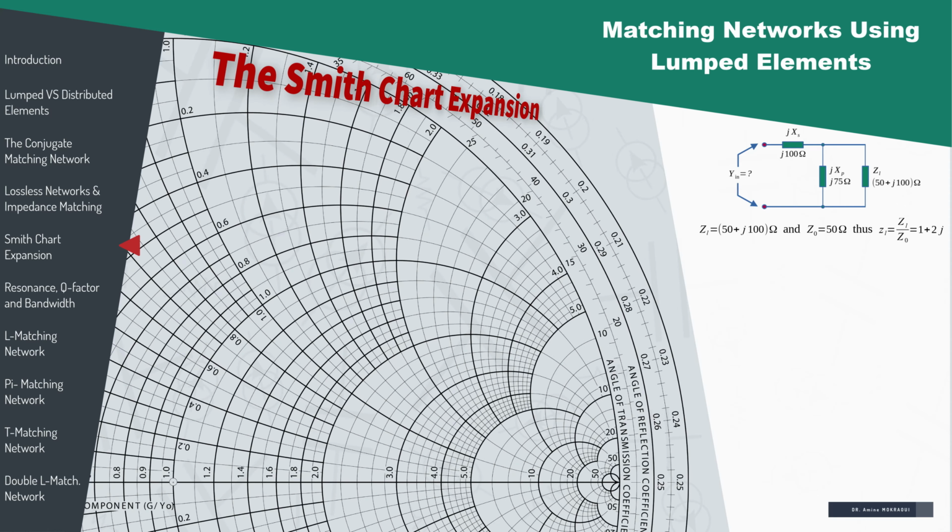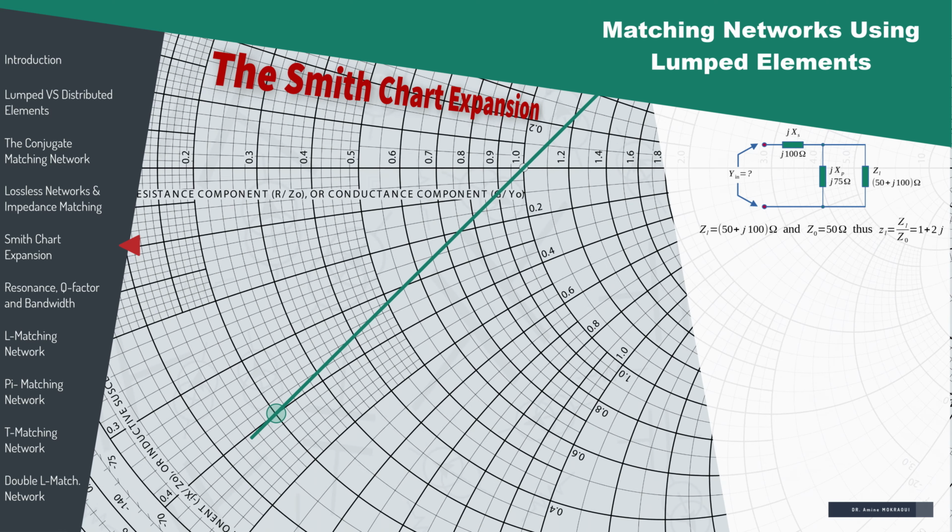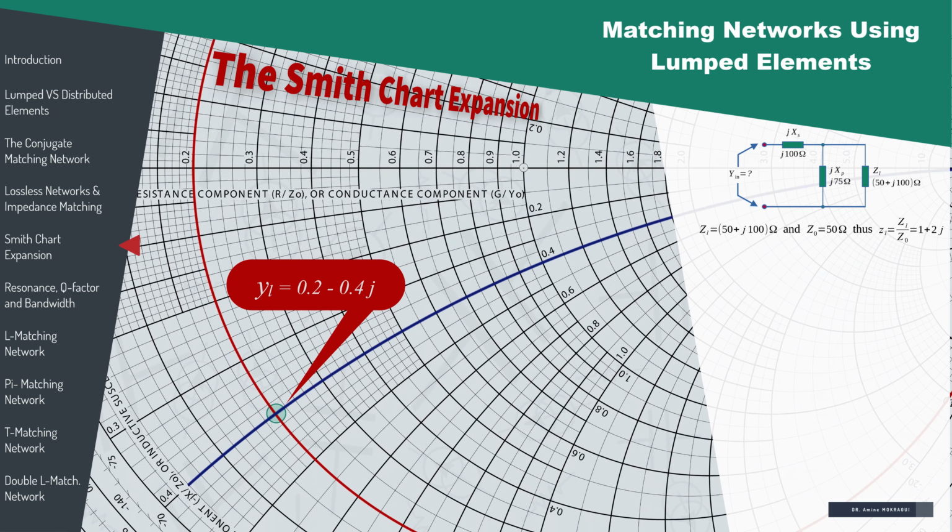The normalized zL equals uppercase ZL over Z0, so zL equals 1 plus 2j. Afterwards, we consider the corresponding admittance using the point diametrically opposite relative to the origin. We find yL equals 0.2 minus 0.4j. The same steps apply to the reactance ZP.